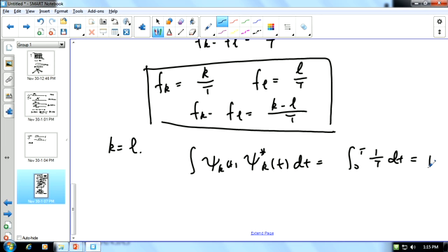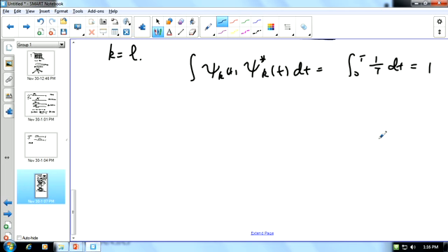So for these signals, their Fourier transform is actually a sinc function, which takes the entire spectrum, which means there will be significant frequency domain overlaps. But the signals are orthogonal to each other. So what we do is, for example, the information from user k is s_k. We multiply it with phi_k(t). And then all the users can transmit simultaneously.